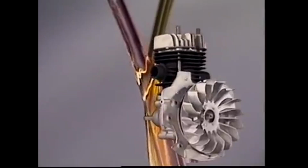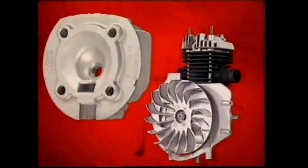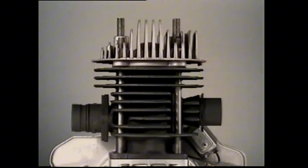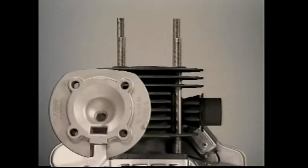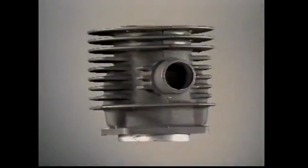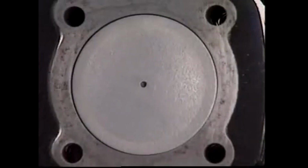Combustion chambers in the cylinder head come in many different designs. To help hold in the extreme heat and pressure of combustion, a seal is made between the block and cylinder head by a head gasket. The 4-stroke petrol engine has other passages cast into the head to carry oil for lubrication and coolant for cooling. In a 2-stroke petrol engine, lubrication occurs by mixing oil with the petrol, so oil passages are not needed. And if, like many 2-strokes, air cooling is used instead of liquid cooling, there's no need for coolant passages in the cylinder head.